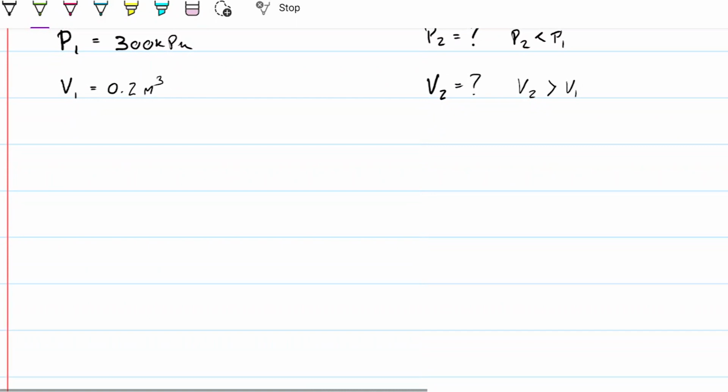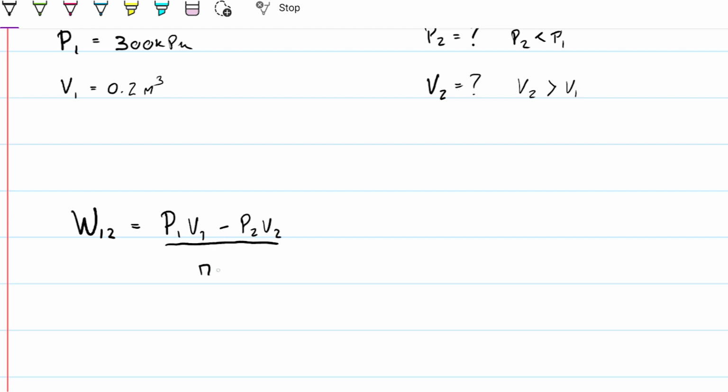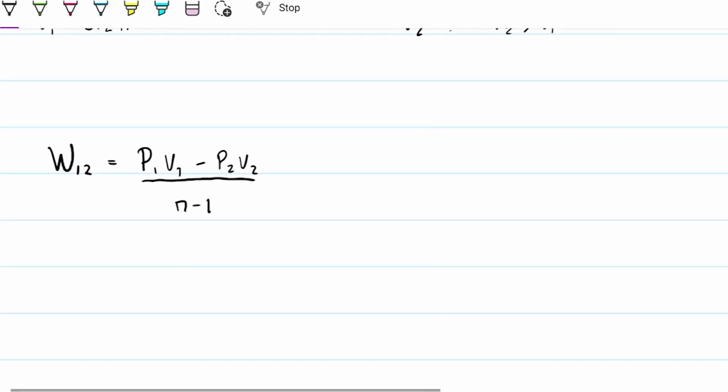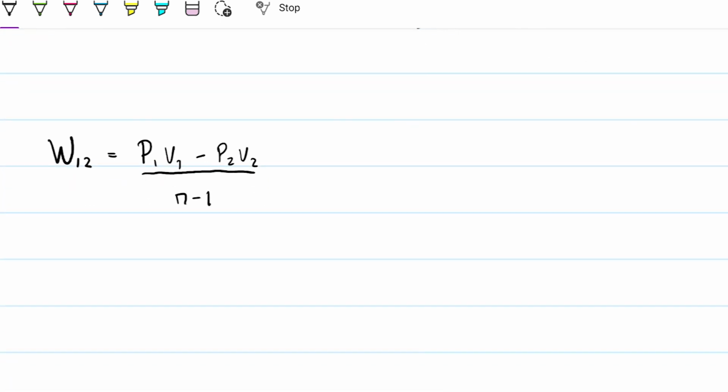Okay, so if I wanted to know the work as I went from 1 to 2 for a polytropic process, that will be, as we just saw, P1 V1 minus P2 V2, divided by n minus 1. Again, you can check the previous video if you're confused by this. Obviously, this is the same as P2 V2 minus P1 V1, divided by 1 minus n. Some people prefer it in this form. It's up to you, whatever rocks your boat.